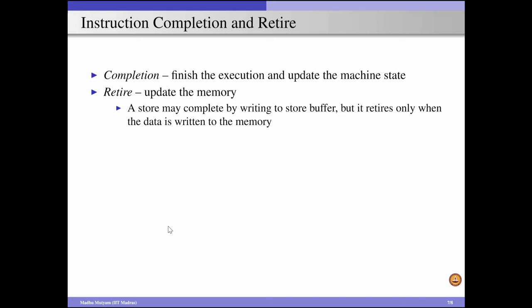The retirement stage is only for the store instructions, and this retirement stage will take the instruction from the store buffer and write it to the memory whenever the memory is free. We also know that among the load and store instructions, loads are critical from the performance point of view and the stores are not so critical.